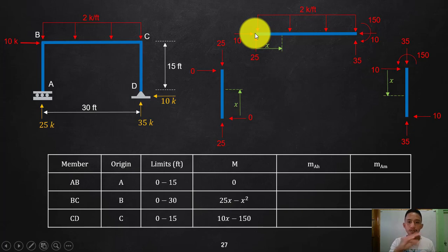So that is just of course your member forces, recalling your theory 1. So we have now here from 0, we have now the 10 again because of that force here. So that is now 10 going to the right. And then of course your actual loading here, which is a UDL, 2 kips per feet. And then of course getting the reactions on the other end, summating horizontal, you will have that going to the left 10. This is correct. Summating vertical, since this is load, you can combine that one and then subtract 25, you will end up with 35. 2 times 30, since the length of that is 30, so that is 60, minus 25, so still going up, which is 35.